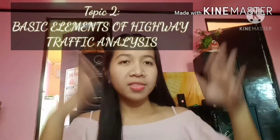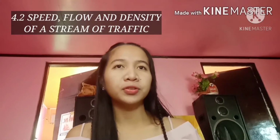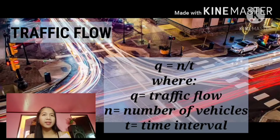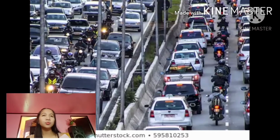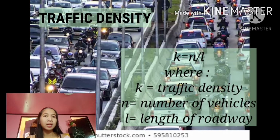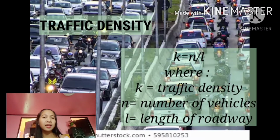So for basic elements of highway traffic analysis, we have these properties wherein dito minemeasure yung highway effectiveness. For speed, flow, and density of a stream of traffic, we can compute for the traffic flow as shown in the formula, which is Q = N/T. Q is the traffic flow, N stands for the number of vehicles in a given time interval. And also, we can compute for the traffic density by using K = N/L, wherein K is the traffic density, N is the number of vehicles, and L is the length of roadway.